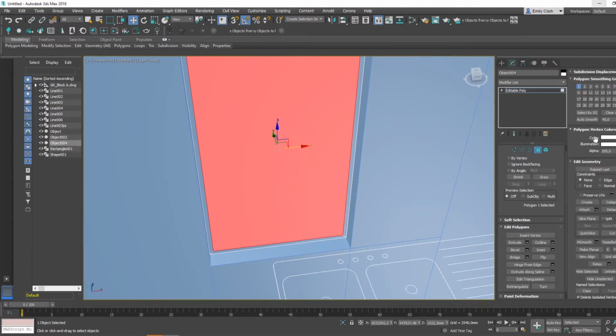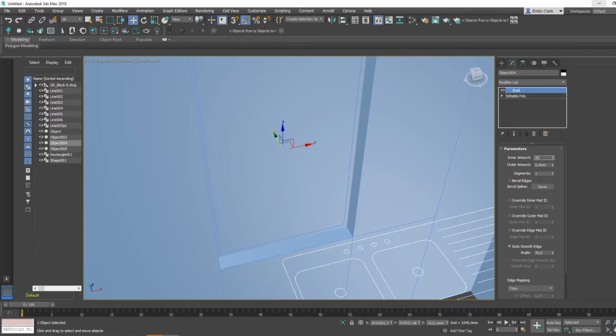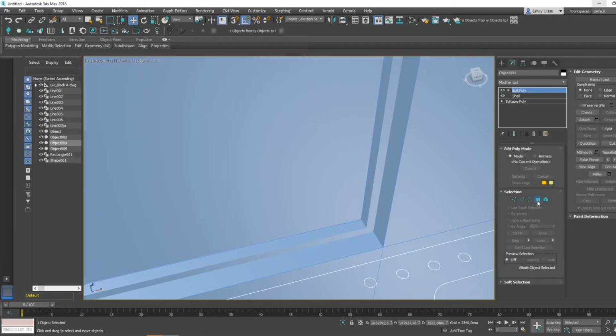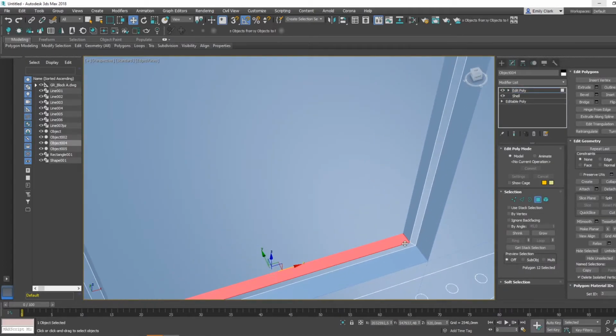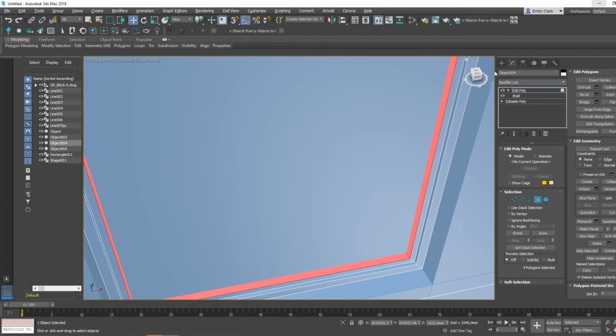Then we go to detach in your edit geometry. Say OK. Then we make this frame a shell. I'll make it about 30 on each side. Once again, you make that an editable poly. Give it a bit more definition. So I'll select the faces. I'll hold shift to loop them. Inset again, a small amount. Extrude by local normals so they all come out the same. And we'll make that as well about 20.